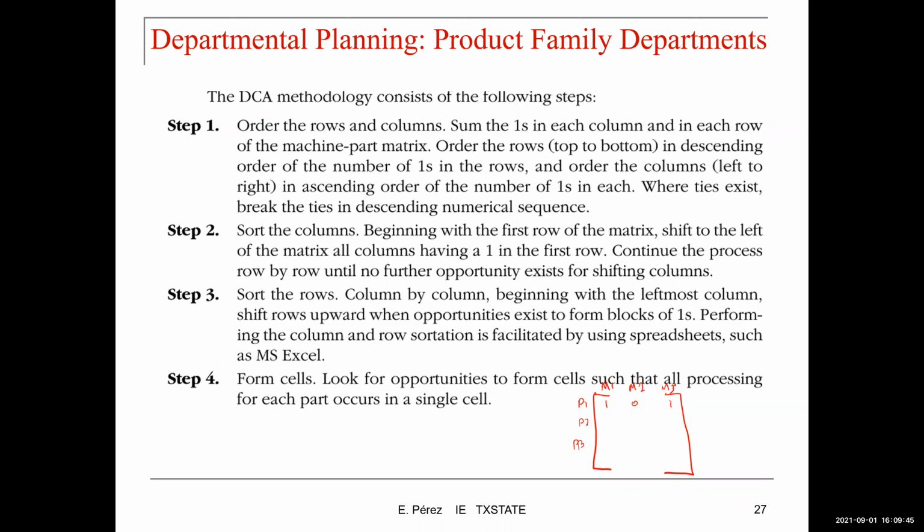So this algorithm is going to allow us to plan manufacturing cells. Basically, we want to build these cells and tell the department, okay, we build a cell that can be used to process part types 1 and 2. And then we build another cell that can be used to produce parts 3 and 4. Okay, so we want to make the minimum number of cells possible. Well, not necessarily. We want to group the products on cells so we can minimize the number of machines that we need to buy or have inside the department.